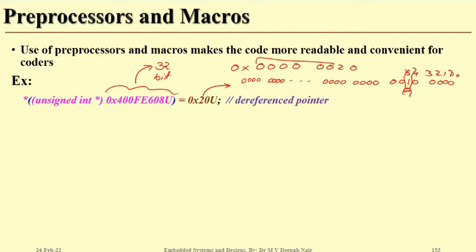Port F. Why port F? Because all the LEDs and switches are on that port, which we decoded from the data sheet of the microcontroller board. Similarly, if tomorrow you are going to work with another microcontroller board, you will have to take the data sheet of that microcontroller. Of course, this same TM4C123GH6PM will be used in many different microcontroller boards, but each company may use different ports to connect the LEDs or switches. So in that case, you must know where the LEDs and switches are.